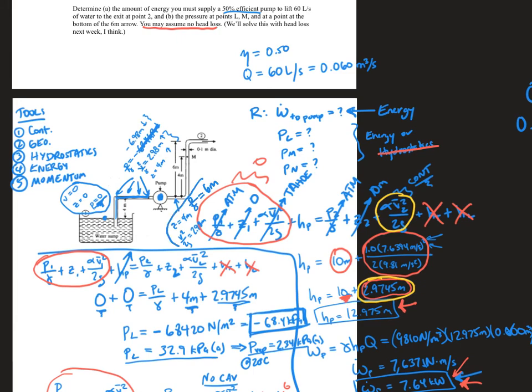Okay, well now we're all positive, right? And we have to be positive because otherwise we're not going to be able to climb this little mountain right here. Okay, so total now we've got 12.98 meters of head. Okay, and it's all because the pump added head, right? Because we started at 0 and now the pump has added 12.98 meters of head. Okay, which is divvied up by 4 meters of elevation, almost 3 meters of velocity, and 6 meters of pressure.